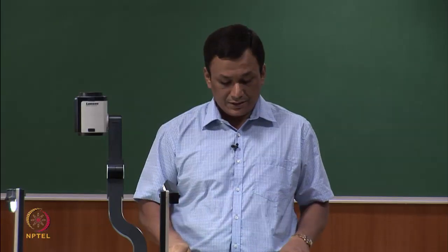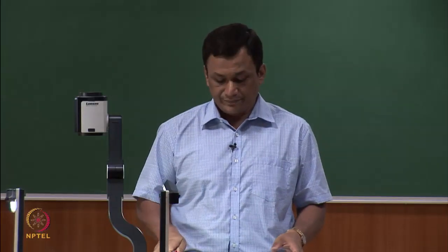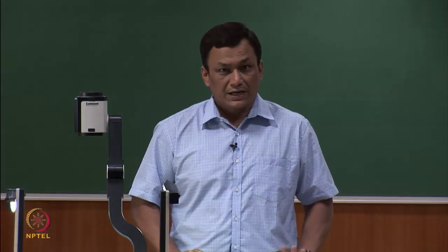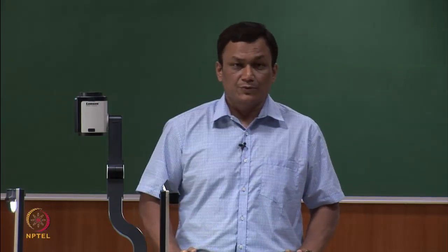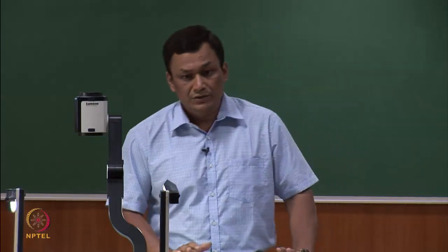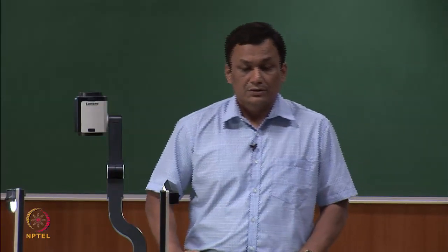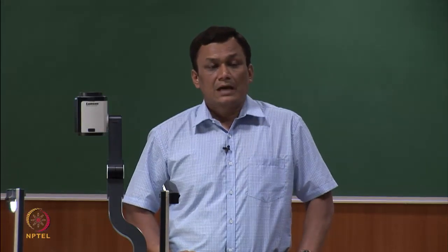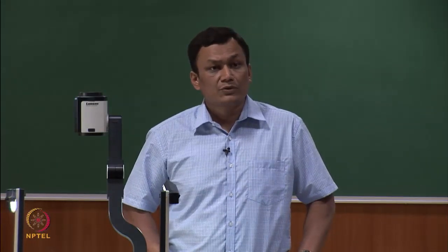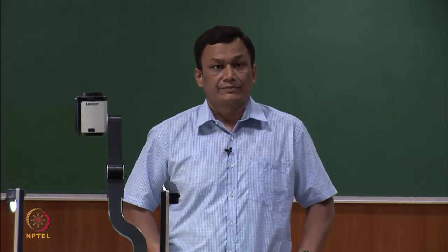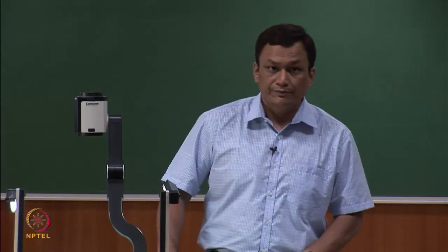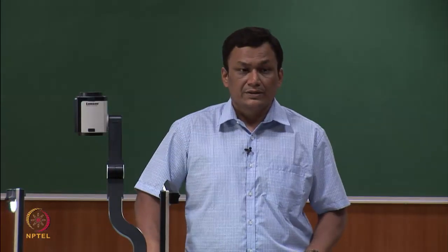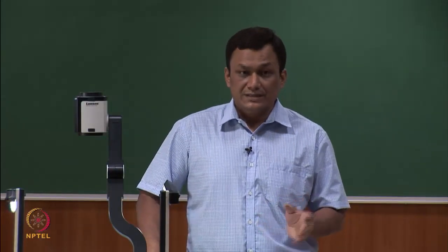So, if we summarize module 3, the aim of this module was to find a relation among yarn twist, yarn count and yarn diameter. As I told you, fiber packing density in yarn basically dictates this relationship.